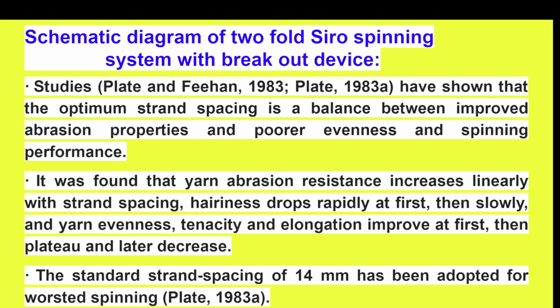Platt and Feehan in 1983 and Platt in 1983 have shown that the optimum strand spacing is a balance between improved abrasion properties and poor evenness and spinning performance. It was found that yarn abrasion resistance increases linearly with strand spacing.